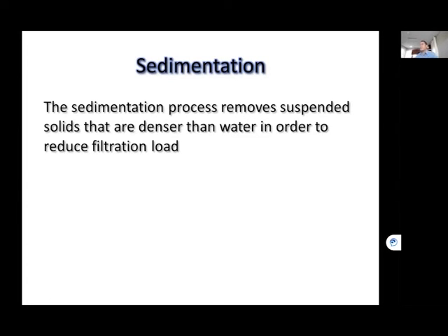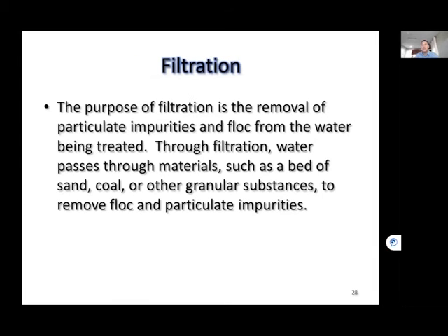So flocculation. After coagulant is introduced, you'll begin to form floc. The flocculation process is used to slow down the water to form a strong floc so that in the sedimentation process, your floc can settle and be removed from the water that then goes to your filters. I'm not going to focus too much on the flocculation sedimentation process because this class is geared more for the T3, T4 range.